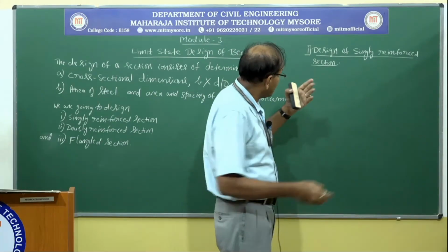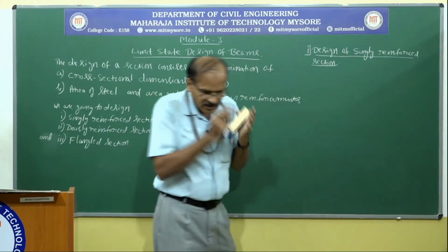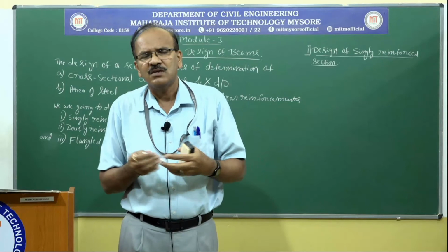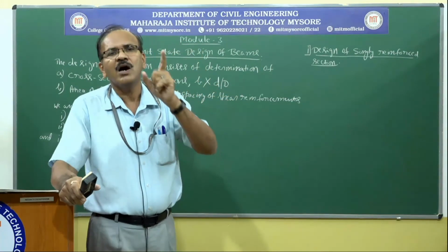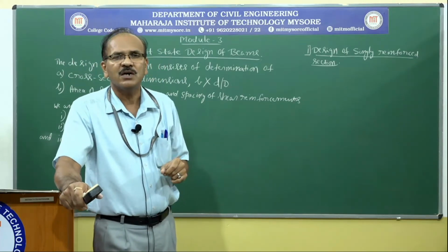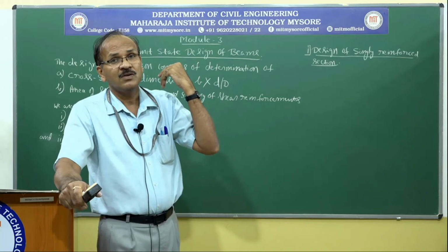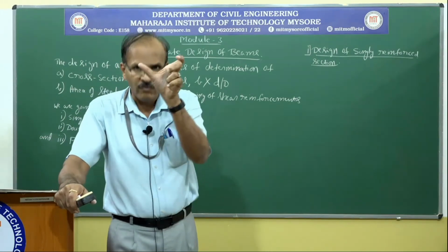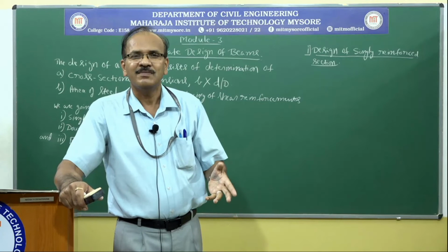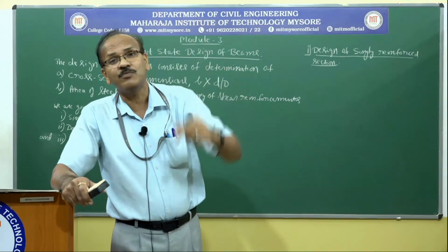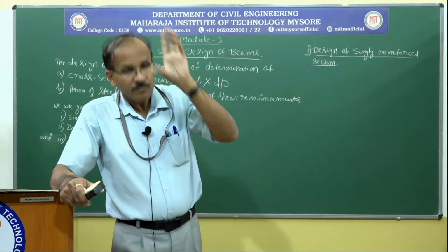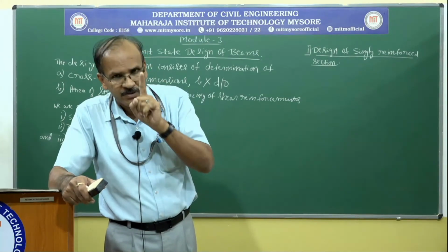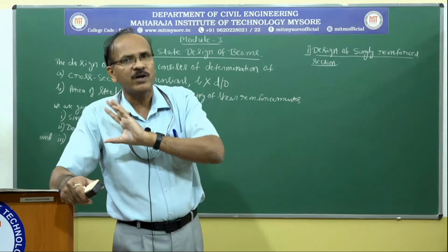In some cases, or even in the majority of cases, some dimensions of a beam are fixed based on architectural requirements and also practical requirements. Sometimes you will be given a beam section saying that the beam should be of this much dimension, that is, width should be this much, you cannot go beyond that, and they will give the depth restriction because of the headroom problem. They say the beam should be of this much height, you cannot go beyond that. So in such cases, we cannot play around or modify the dimensions.